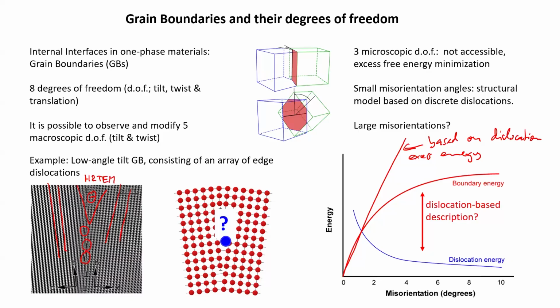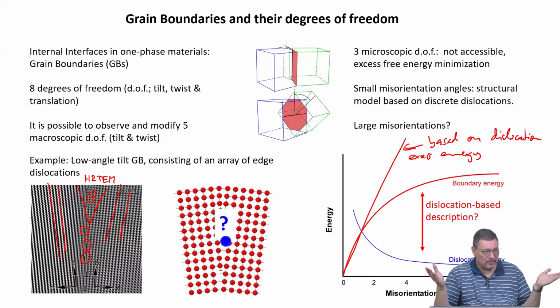Like if my grains have twins also. I am calculating my misorientation through EBSD. That gives some misorientation, which includes this twin boundary also. Can I correlate with energy of dislocation? Overall, no, because the twin boundary is a boundary that is very special. It has much lower excess energy, so it's almost zero, because if it's a perfect coherent twin boundary,